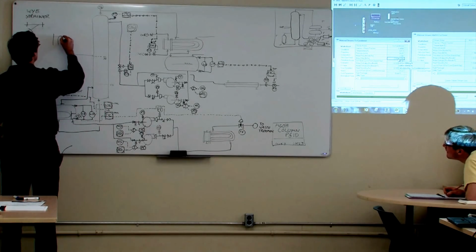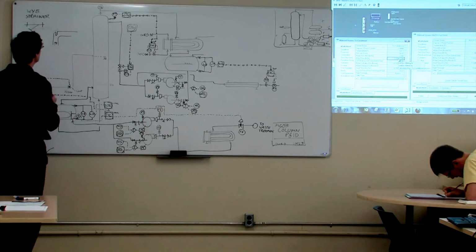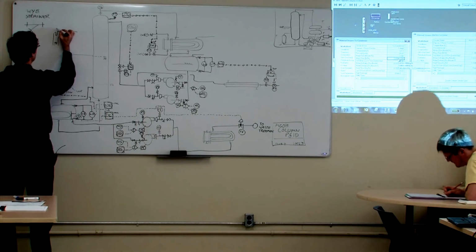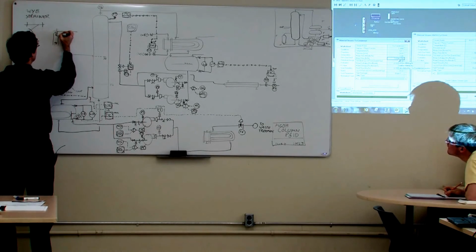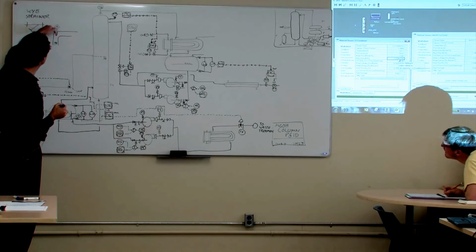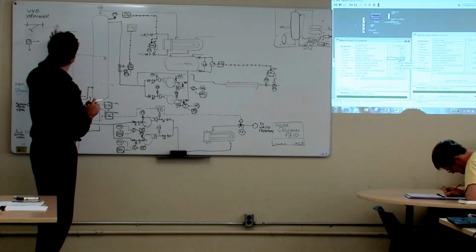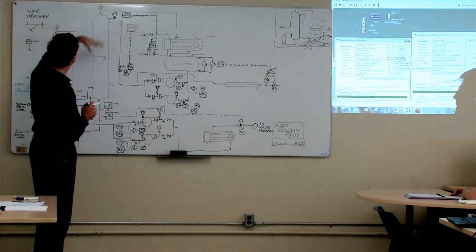So if you've got an elbow like this in a piping system with flow doing this, your thermal well, which is basically what the temperature element sits in. So the thermal well is part of the piping system, and then the temperature element fits into the thermal well like that. And for you to have faster response, you want the thermal well to be facing into the fluid flow, so there's high velocity and lots of turbulence around it. It'll give you a faster response. So I'm going to put it in the piping. You could also put it in the tower itself.